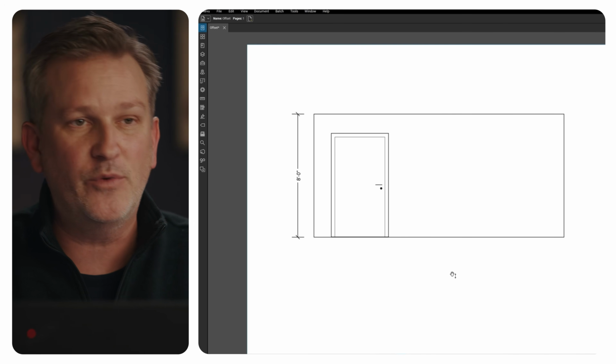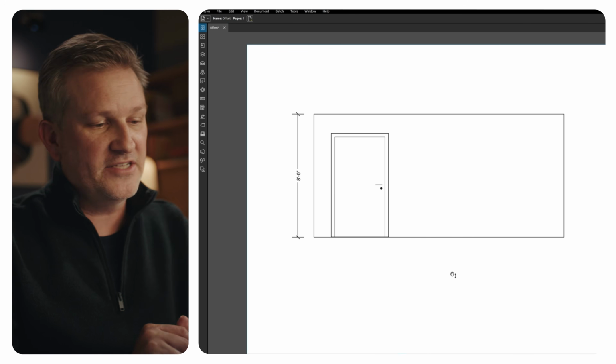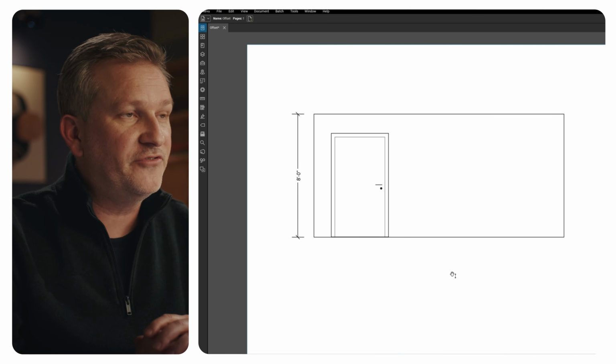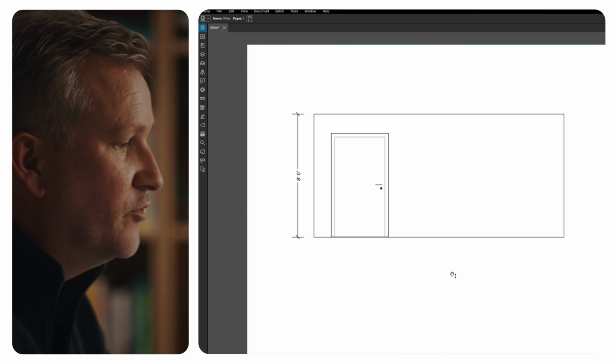Now, the Magic Markups are made up of 3 separate tools: the Offset tool, the Convert To tool, and the Duplicate As tool. Let's start with the Offset tool. Now imagine you need to do an installation, and you want to make sure that you're providing the right documentation for exactly where something's supposed to be located. In this case, we know that there's something to be installed exactly 36 inches off the floor and 22 inches off that right door jamb.